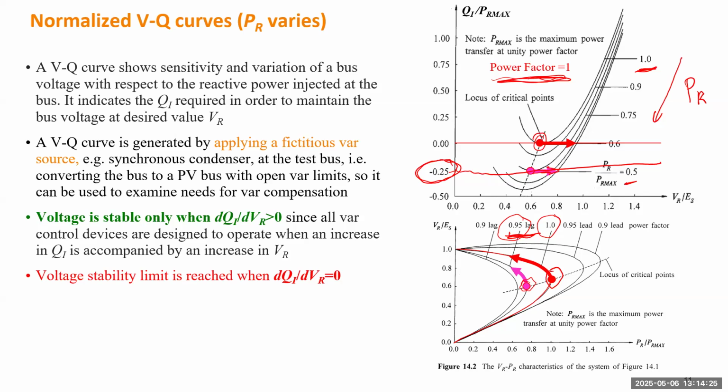So this just gives you an example of the PV curve and the VQ curve for the same system. They do have a very strong linkage. It's just a projection to different spaces, depending on which space is useful for your study. If you want to understand how far away from the boundary, the PV curve will be very useful. If you study how much control will be needed, the VQ curve will be good.